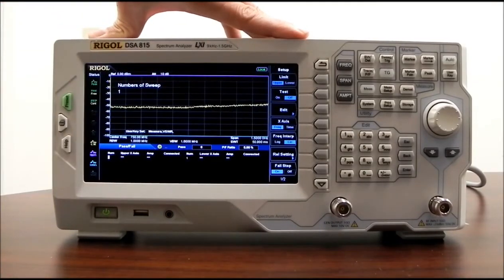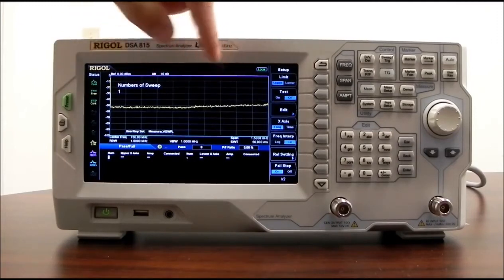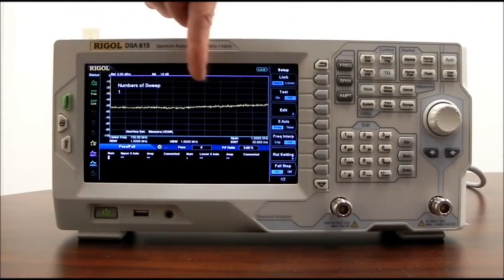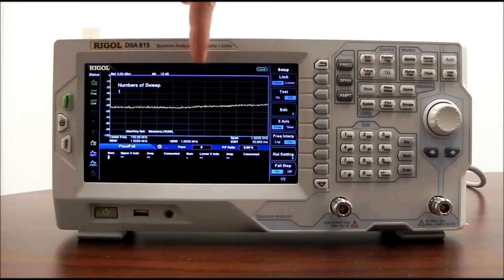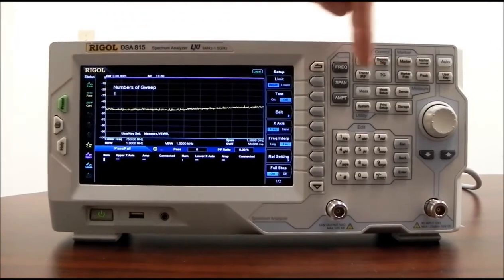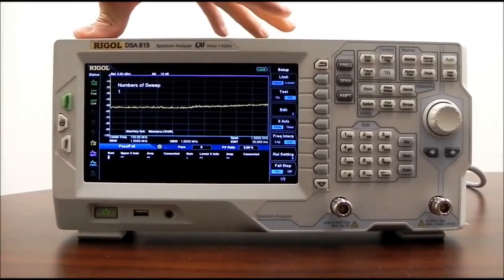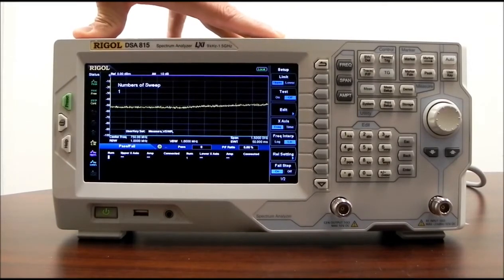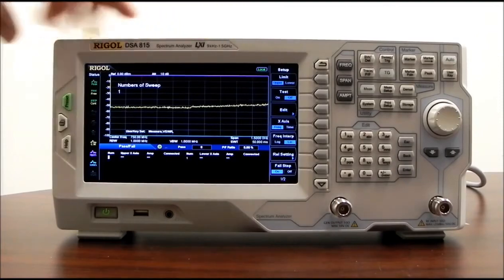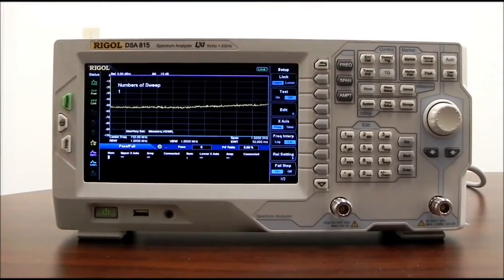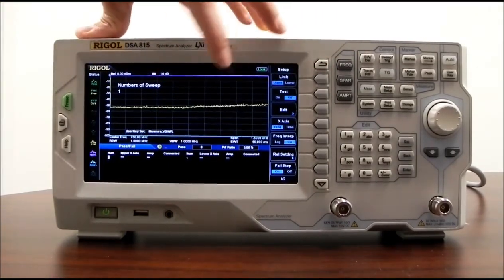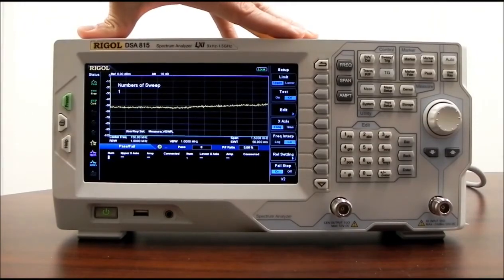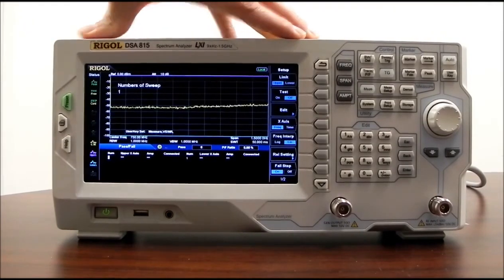You can use this to actually build a window around a particular channel. Let's say we were doing frequency modulation. We could build a window around the frequency modulation, and if that frequency went outside of the upper limit, it would be a fail. Or we could also use the limit lines, upper limit lines especially, for EMI and EMC compliance. We can have a dB value that cannot be exceeded at a particular frequency range, and if we were to pass over that value, we would have a failure.